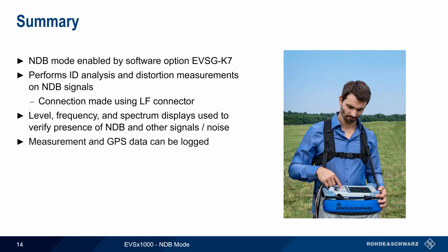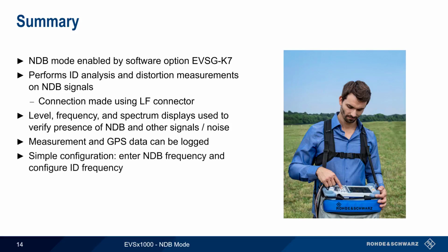All measurement data can be logged together with GPS time and position information. And finally, configuration of NDB analysis is very easy. Simply enter the NDB frequency and configure the frequency of the ID signal.